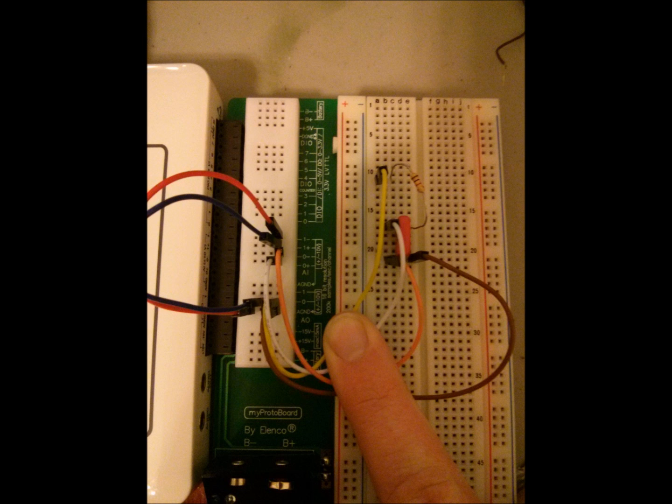Here's a picture of a circuit constructed on the MyDAQ. AO is used to supply voltage to the circuit and AI is used for the oscilloscope. The yellow wire goes from AO0 to one end of the resistor, and the brown wire goes from AGND to one end of the capacitor. The white wire goes from AI0 plus to the end of the capacitor that is closer to the resistor, and the orange wire goes from AI0 minus to the other end of the capacitor. The blue wire goes from AI1 plus to AO0, and finally the red wire goes from AI1 minus to AGND.